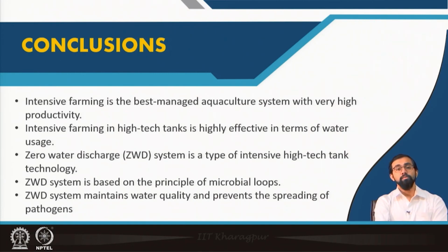We can take it to a different level when we go for designing this kind of zero waste disposal or zero water discharge systems. This kind of ZWD system is based on the principle of microbial loops, as I already discussed in the last slide. It also maintains the water quality and prevents the spreading of pathogens altogether, because whatever amount of pathogens can be present in the system, it is possible for them to be utilized by the heterotrophic microorganisms.